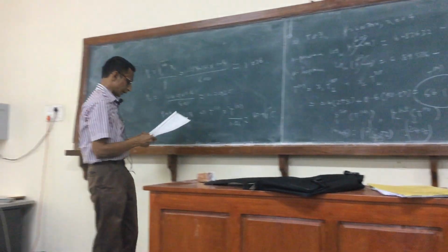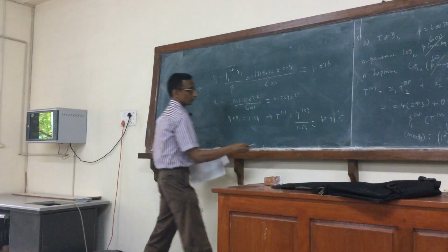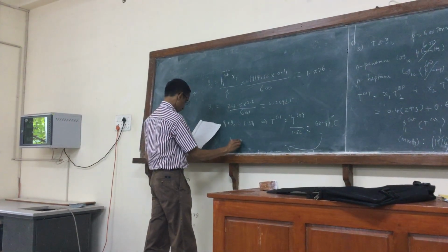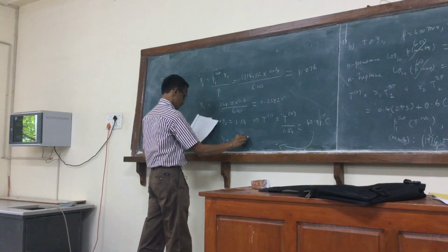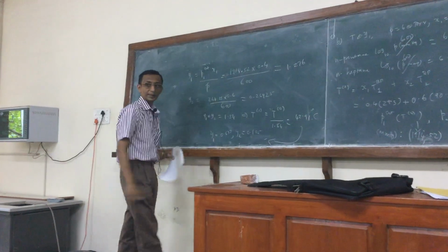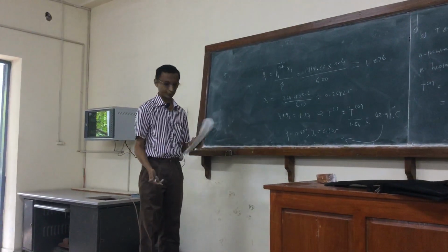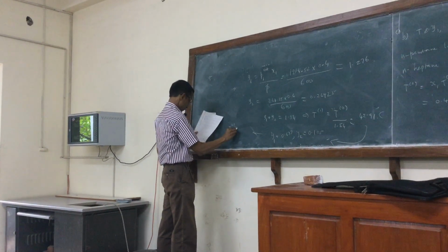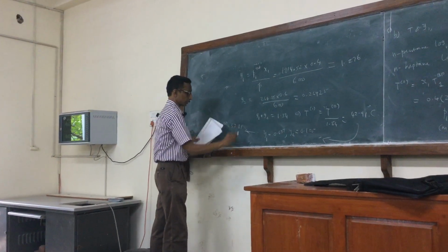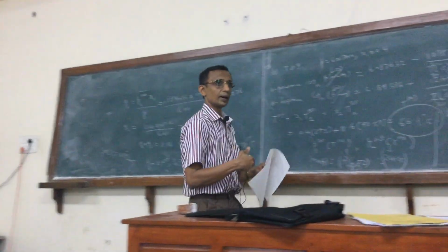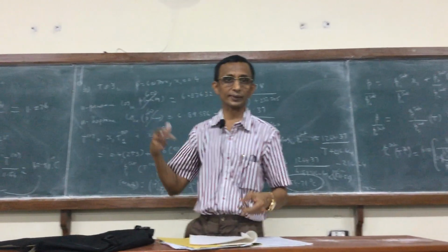And then if I do that, y1 turns out to be 0.637 and y2 turns out to be 0.105. Now it has become less than 1, so I will increase the temperature. And T2 can then be shown to be equal to 57.81 degrees centigrade. So it's sort of oscillating, as you can see. And you can easily check the convergence rate.